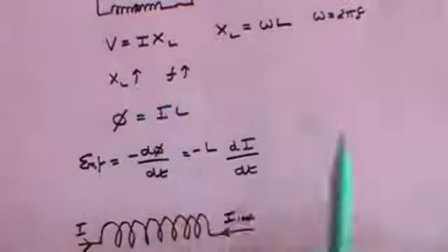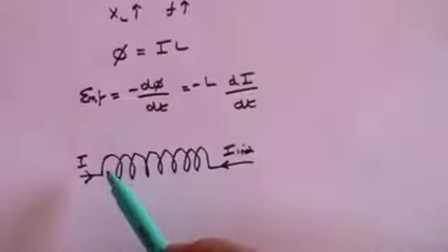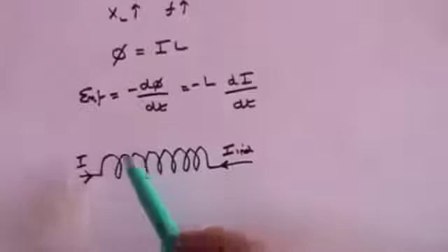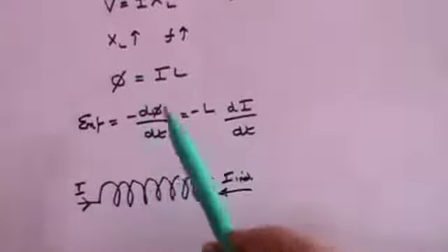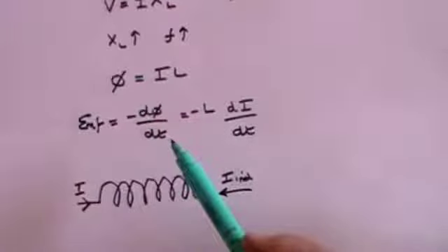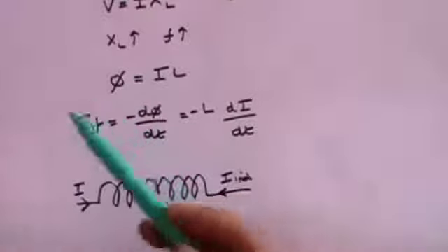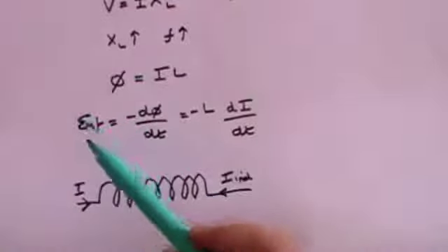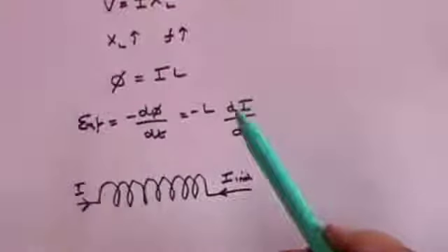Now, why therefore should it be that as the frequency increases, the reactance, the resistive effect of the inductor, should also increase? Well, think, the higher the frequency, the more rapidly the magnetic field is changing, which means that the rate of change of flux is greater. So if you have a greater rate of change of flux, you'll have a greater EMF, and that greater EMF will produce a greater induced current.